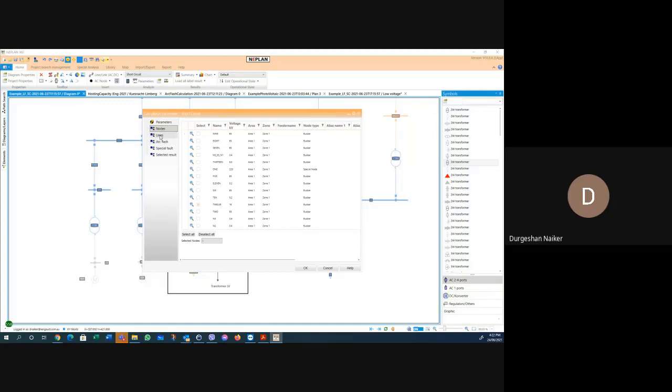Okay, is there any short circuit in a line? Now, obviously, you don't have short circuit only on the bus bars or nodes. You can also have it in a cable. In other words, there's a cable and probably 20% from the start, or whether you want to say in percent or meters away from the area, there's a short circuit. So here you can see line 5 and 6 over here. We said there's a short circuit at 50%, which means right at the halfway point, whatever the length of the cable is, half of that there's a short circuit at the halfway point. It could be 3/4. It doesn't matter. In this particular example, we got 50%. Okay, so what do you want to know?